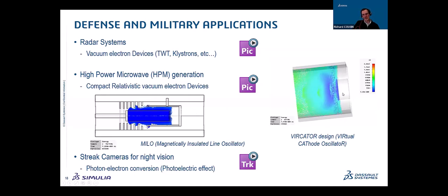Here the high voltage generator creates a high voltage pulse, which propagates here. We have some electrons moving towards a grid. And while the electrons are passing through the grid, they create a virtual cathode, and the oscillations of the virtual cathode are then capable of emitting a microwave pulse